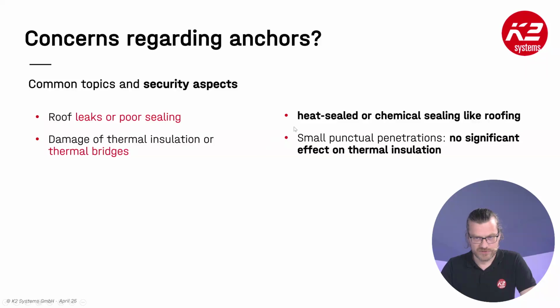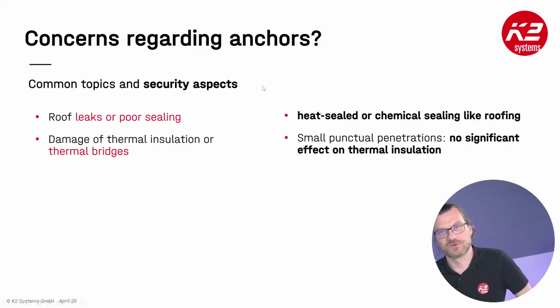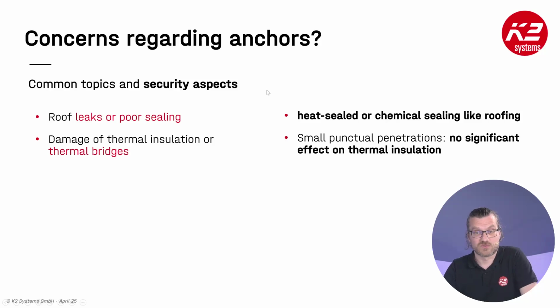Thermal insulation, thermal bridges. It's also an important point. People are afraid that if you put the screws through your insulation, you will lose a lot of warmth during winter time. Our answer to it is that these penetrations are so small that there will probably be no effect on thermal insulation at all.